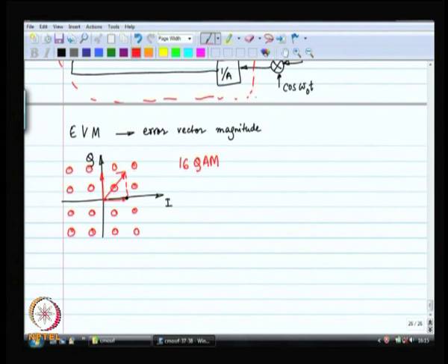And so, if you have made a mistake in this phasor, if the I path has gain that is different from the Q path, so you probably wanted to go over here, but your I path, let us say, has more gain than the Q path. The Q path has less gain, which means you will come somewhere over here.